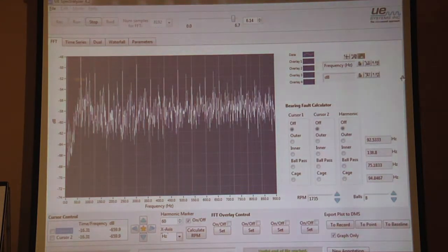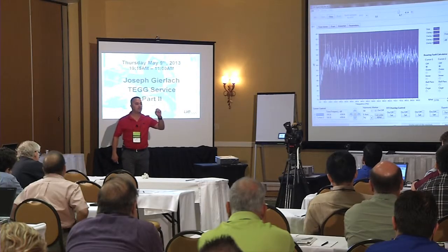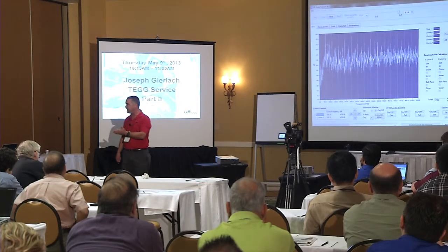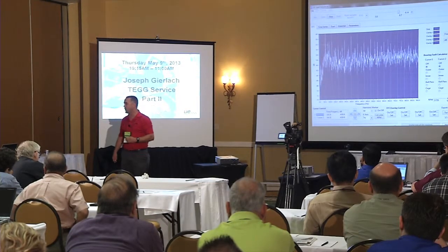Everybody knows this if you've been through a level 1 class. So nobody's taken a level 1 class? You see a lot. Matter of fact, almost all these 60 hertz harmonics hit, don't they? Every one of them, because the ionization is taking place at the highest peak of the sine wave. And where that stress is greatest, it's a predictable, in this case, 16 millisecond time base. The FFT produces a nice picture of all those harmonics.